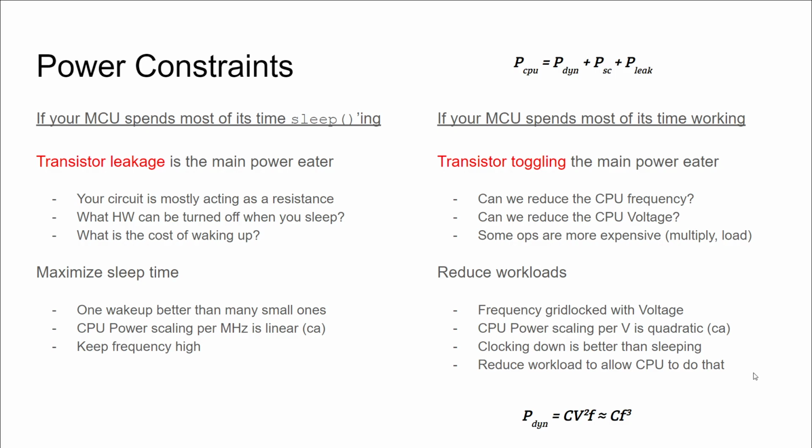Some MCUs come with DVFS, that's Dynamic Voltage Frequency Scaling. This is a concept where you have some controller deciding the frequency of the MCU, and input to this controller typically includes the current temperature of the MCU, but also often how often the chip is used, as in usage uptime. There's actually two types of MCUs out there.